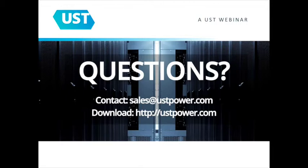What are the typical battery replacement time and costs when you compare that to the UST EVR? Well, what we would expect with the addition of the EVR, we would extend the battery life 20 to 40%. So if normally you'd expect to replace the batteries in 3 years, we would be able to extend that to 4 or possibly 5. And with that extension or reduction in cost, that would more than cover the cost of the EVR.